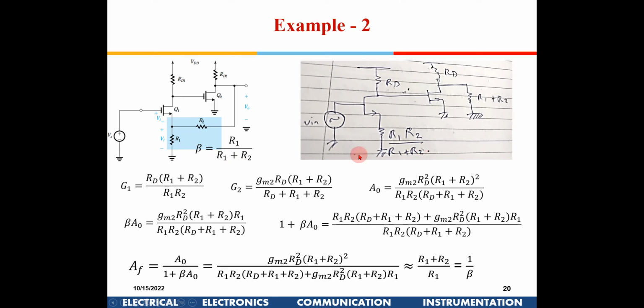Sir, can you explain this again? How is the output side coming? The input side, I got it. I remove this circuit. What about this current source? This is a current source, right, in small signal. If there is no voltage applied to the gate, this current source will go off, right? So I will have R1, R2 to ground. Yes. So this will become series.